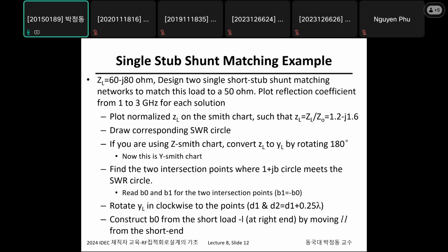If you just add a series transmission line with length L, then in the Smith chart it just moves your pointer clockwise by 2βL, right? So by using this, you can control the impedance.